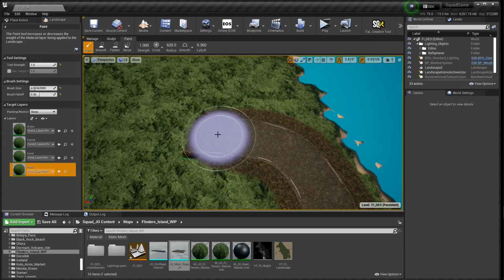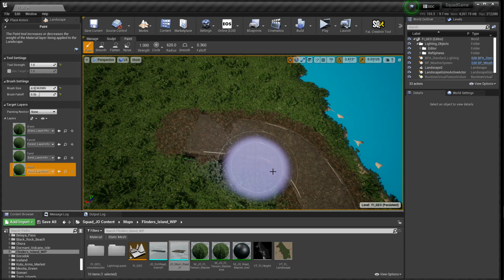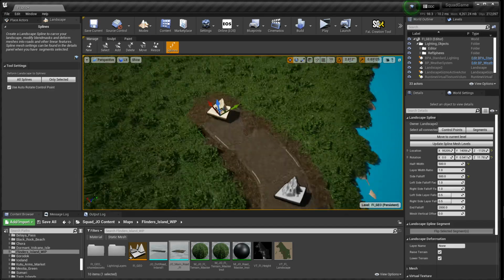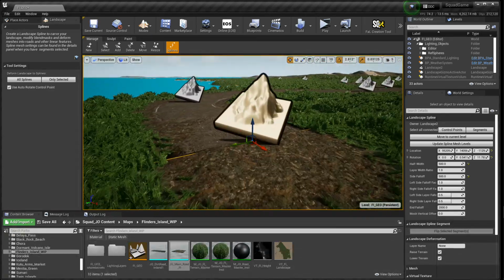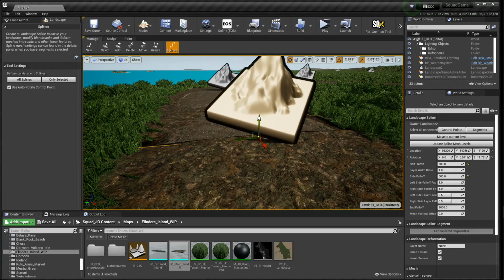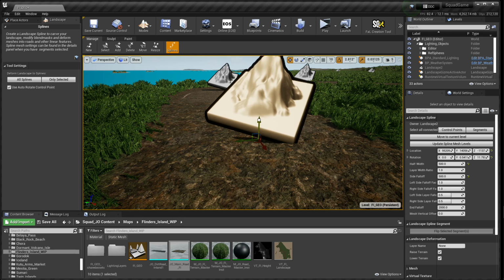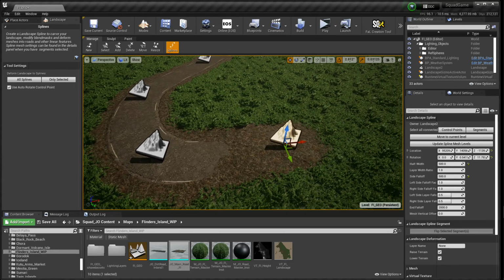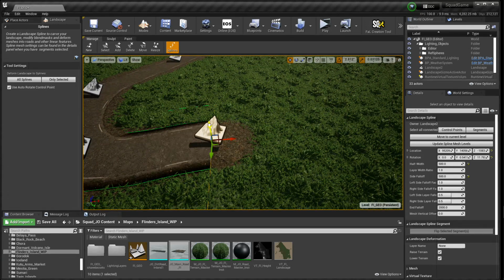And then the last thing you want to do is go back into your spline tool, and at the ends of your roads, where they end, you want to drop the end control point down to hide it, or at least get it so that it's not obvious, and it'll blend that last bit of road in. I'll do it again, hang on, press End to sit it on there.